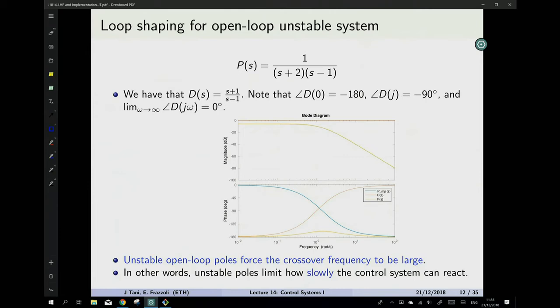So theoretically, there's no problem. If you have an ideal situation, the math works out. In fact, it cancels out. Try adding a little perturbation. Try adding plus epsilon. You'll get an input signal with a part that makes physically no sense. Let's just keep that like that, because this always represents a physical thing that has to act on your system. And whatever you can imagine in this universe, there's no such thing as infinity, okay? So you'll never have infinite current, voltage, rotation, whatever it is that you want to do, there's no such thing as infinite. An infinite input breaks your system at the end of the day.